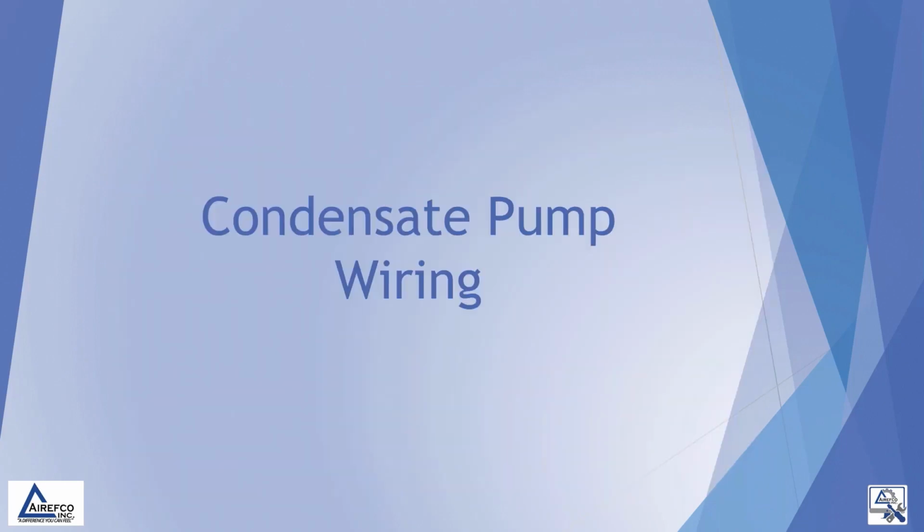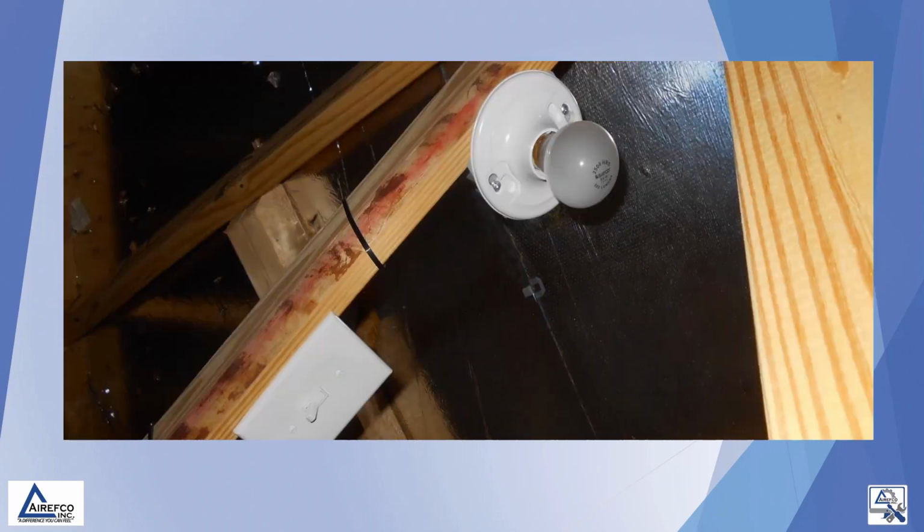Once you've run your condensate piping, the next thing you need to do is wire the condensate pump in. And the way that it's wired in is very important. I had a case a while back where they had a mystery that every time the technician would leave, the homeowner would call a couple hours later and say that the furnace had tripped out on condensate pump malfunction. And then when the tech would go up to the attic and check out the furnace, everything was fine. He'd leave, and a couple hours later, they'd get a call that the furnace was out again on condensate failure.